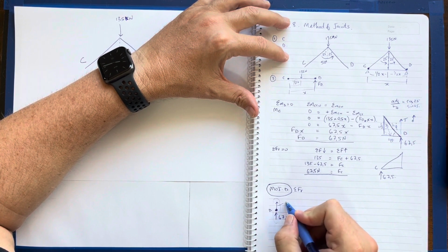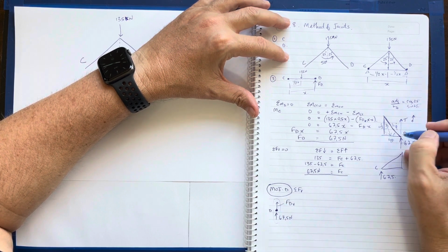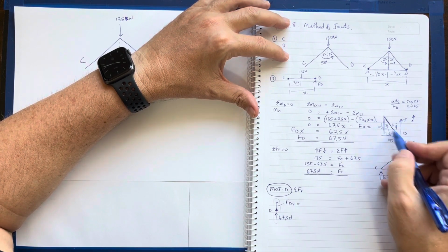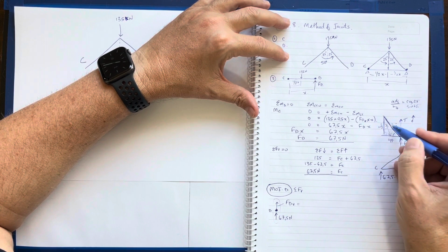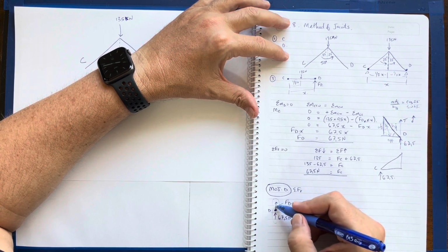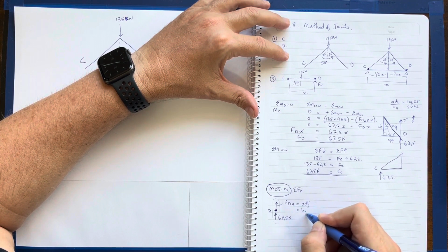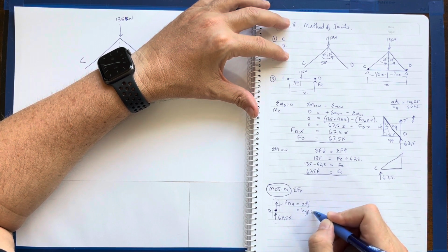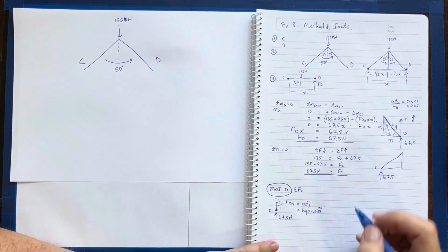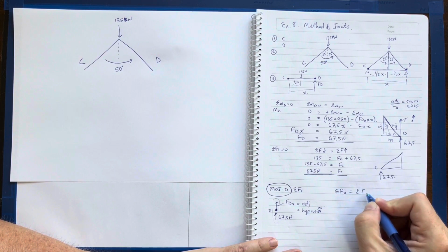So this is going to be my force of D, but the vertical equivalent, which equals, that's my hyp. That's my hypotenuse of this. And adjacent over hyp equals cos. Therefore my adjacent, because I'm looking at the vertical, that is the vertical itself, it is the adjacent, which also equals the hypotenuse cos 25 in this particular sense. So the sum of the forces down equals the sum of the forces upwards.